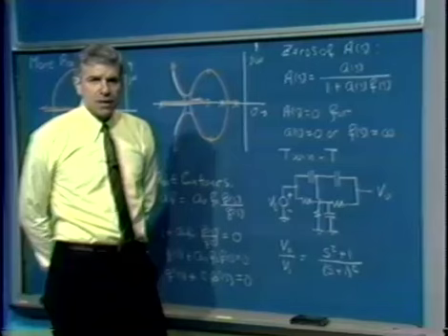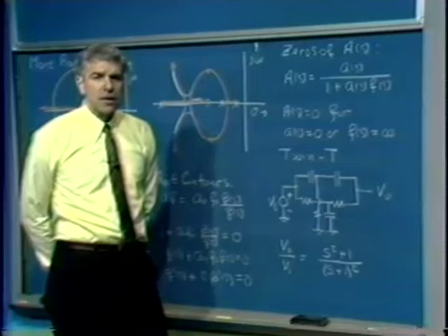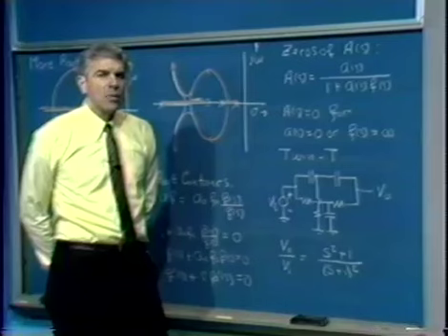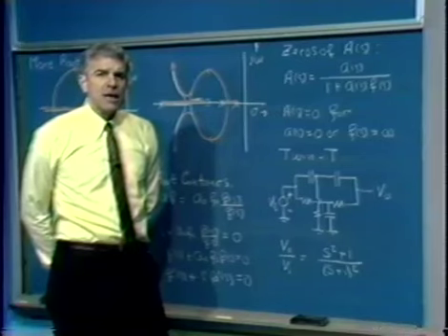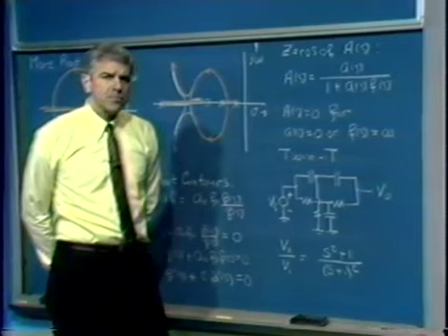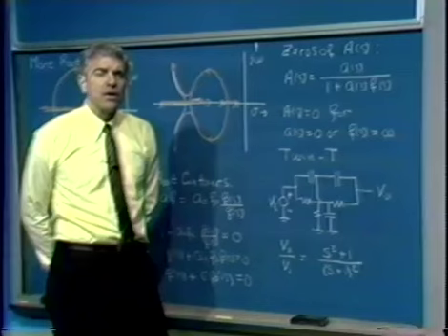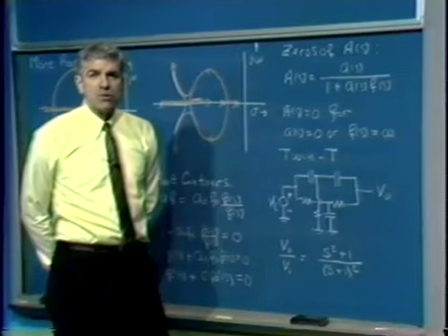Again, by the argument that I earlier used, that the number of poles and zeros has to be the same so that the high frequency gain is a constant with increasing frequency, we'd have to have 3 zeros. If, once again, we select component values correctly, the 3rd pole and the 3rd zero can be made to cancel. In that case, we get a transfer function which includes 2 zeros divided by 2 poles.